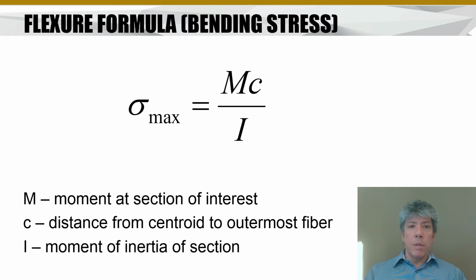The equation we will use for calculating the stress in the beam is sigma, because it's a bending stress. It's a normal stress. You're trying to either pull the material apart at the bottom where it's stressed, or you're trying to push the material together at the top where it's compressed. Sigma = MC over I, this normal stress, is how we calculate it.